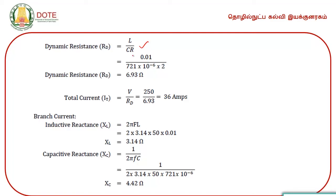So, the dynamic resistance value is equal to L by CR, L is equal to 0.01, C value we have already found out, it is 721 microfarad, and the resistance value is 2. We have the dynamic resistance value as 6.93 ohms. What is the total current? It is the applied voltage divided by the dynamic resistance. The applied voltage is 250, dynamic resistance value is 6.93. So, the total current will be 36 amperes.